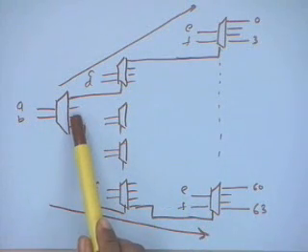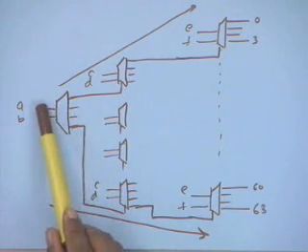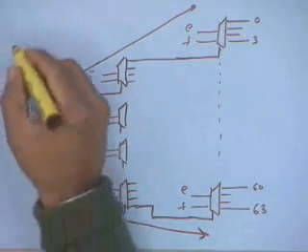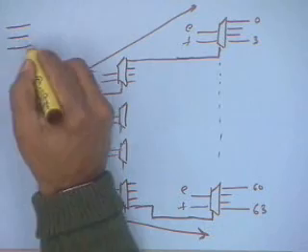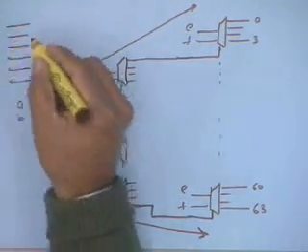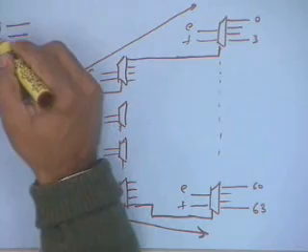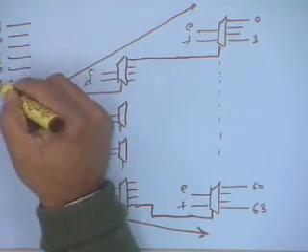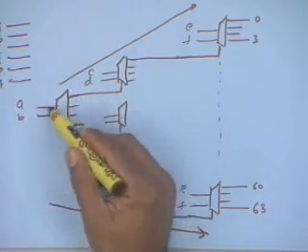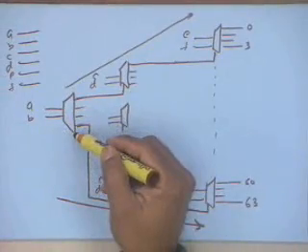So the output of this decoder will take some time to stabilize after the input comes. Typically in such a situation, we assume that all these 6 inputs that we have, they all come simultaneously. In a combinational logic, these inputs may be coming from some source, but typically we assume that they all arrive together. That means this output is going to get stabilized after the decoder delay.